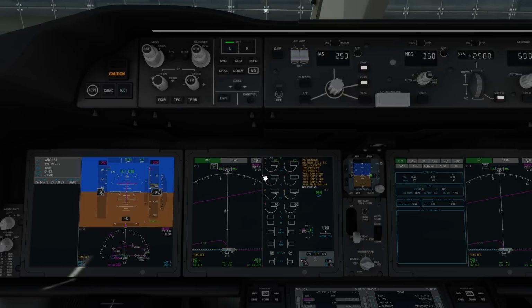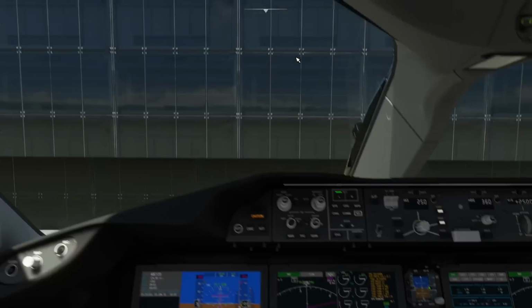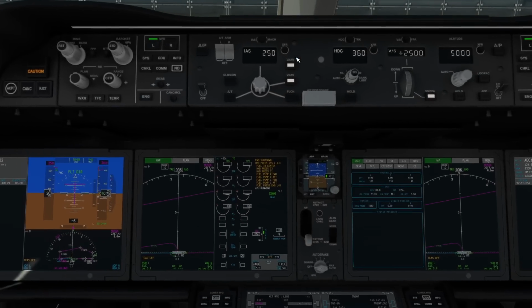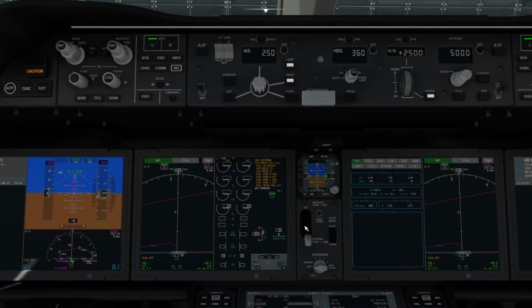So calibrate the altimeter. Oh, yeah, calibrate the altimeters. It's very late here and I'm quite tired, which is why I keep making speaking mistakes. So press B and it calibrates the altimeters for us. Auto throttle goes to armed. So then control 2, we were already on control 2 for this view, but we're actually more interested in what's down here. We want to set the auto brake to RTO.